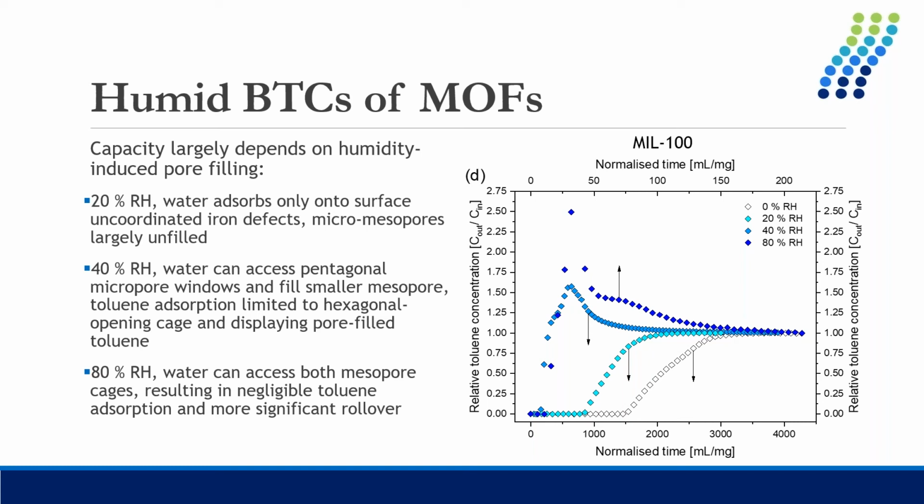So at 20% relative humidity, again, this is before pore filling occurs, water is only adsorbing via surface adsorption onto uncoordinated ion defects, and the micropores and mesopores are largely unfilled. So we see the breakthrough curve shift to the left, but we don't see any displacement occurring.